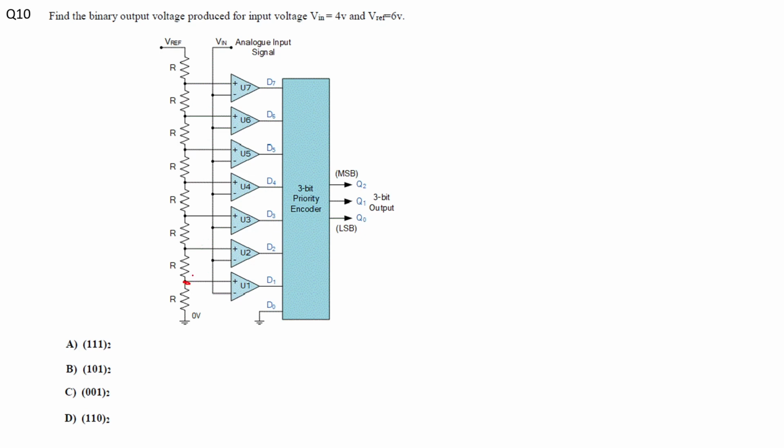So let's just term these voltages as V1, V2, V3, V4, V5, V6 and V7. So your V1, if you use this voltage divider rule, is equal to Vref by 8. Simply this is equal to Vref by 8 because this is total 8R multiplied by R. So Vref by 8R times R, so that is Vref by 8.